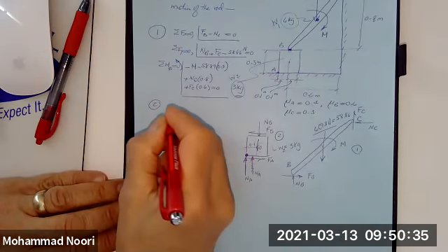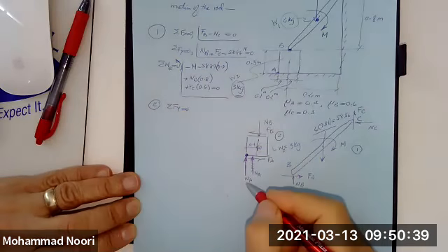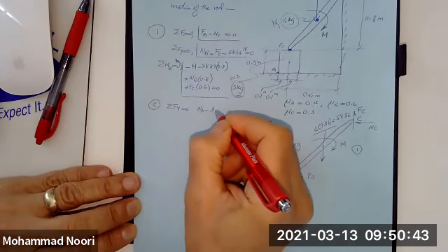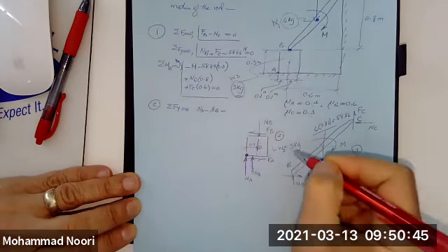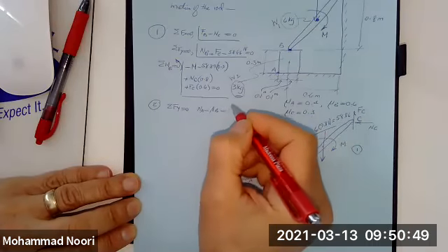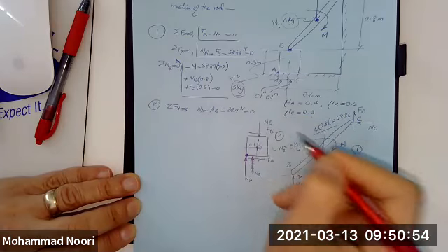So based on that assumption, let's use all the equations of equilibrium here. You have summation of forces along Y equal to 0. That will give you N_A minus N_B minus weight of this block, 3 kilogram times 9.8, that would be 29.4 Newton, equal to 0.